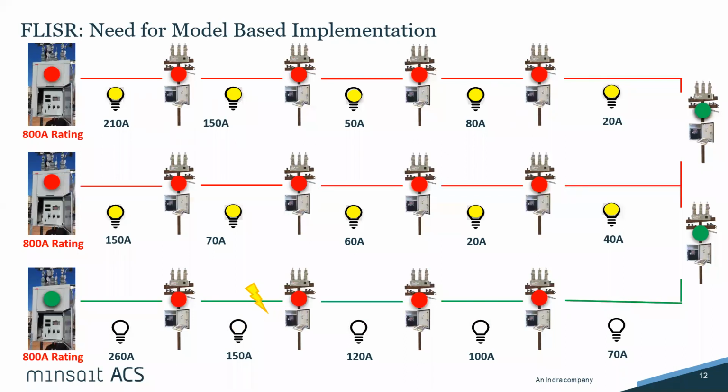So just as we did in the exercise previously, we want to start going through the entire FLISR process. After all the protection, so if you have any reclose enabled, after all that, once we've gone to a fault trip to lockout, that's when you want the FLISR system to take over. Once we're taking over, we're going to look at fault flags, and we will find where the fault is, and that's in that second segment down line of that 3rd feeder. We are going to isolate that fault and then start with the restoration process. So we start with doing an upstream restoration.